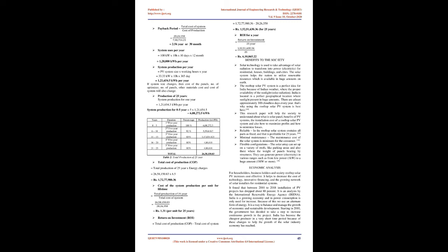C. Roof pitch and roof angle. When designing the solar system, the tilt angle in degrees must be noted. While optimizing the solar system performance, the tilt angle in degrees must be used. When installing the solar system on the roof or ground, keep in mind that the first row solar panel shadow should not fall on the second row solar panel. If you are thinking about installing a solar PV system on your home or office, do not neglect the roof pitch in degrees.